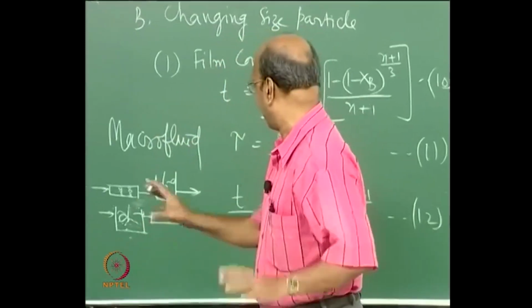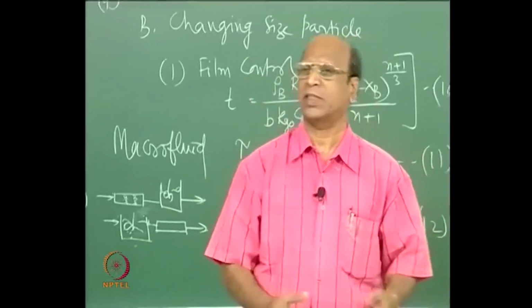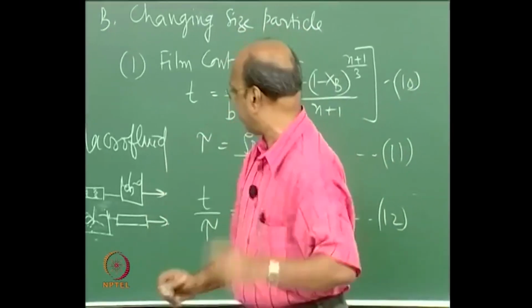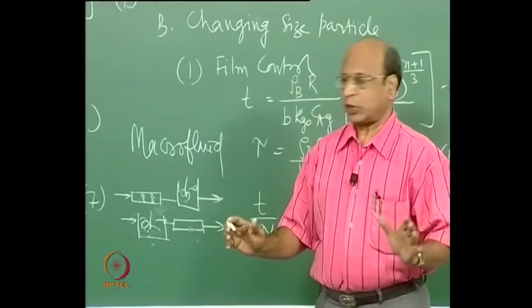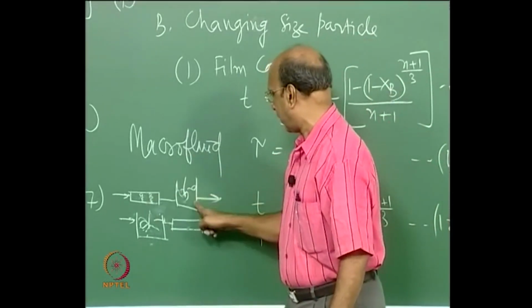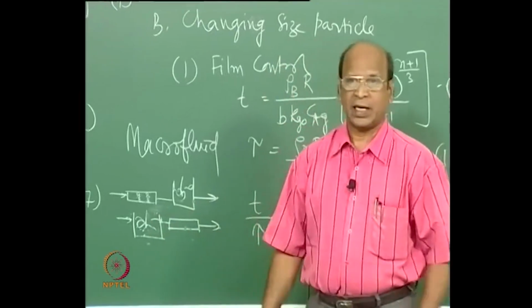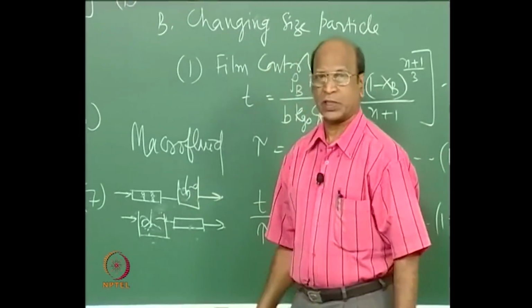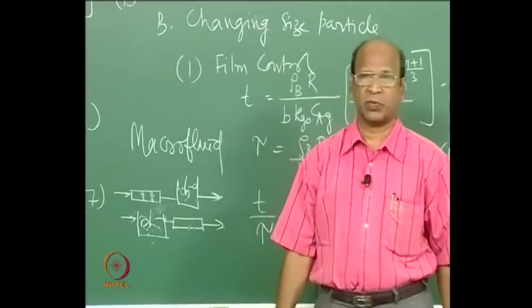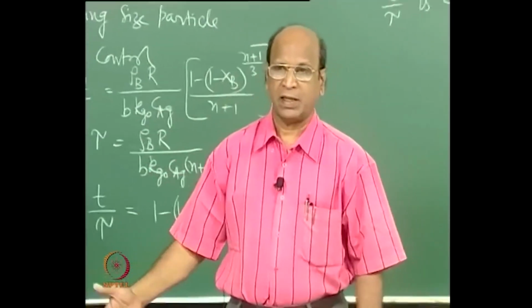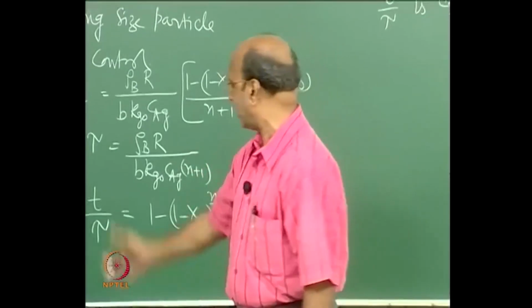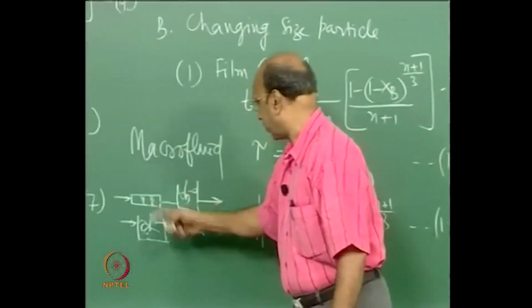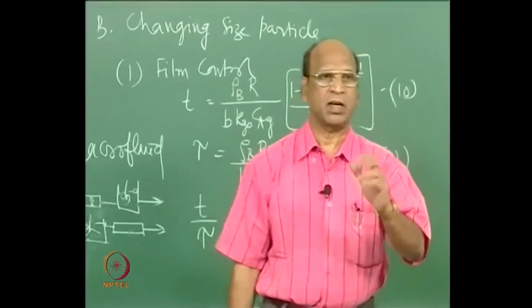I think this is the general information, and you have to remember all this. It is a wonderful concept, and remember this, which will make everything clear. So, if you put first a PFR and then an MFR, and reverse it, you will see that here you have more conversion for second order, here you will have less conversion for second order, and then you have to question why that is happening. That is happening because that is late mixing, this is early mixing for second order reactions.